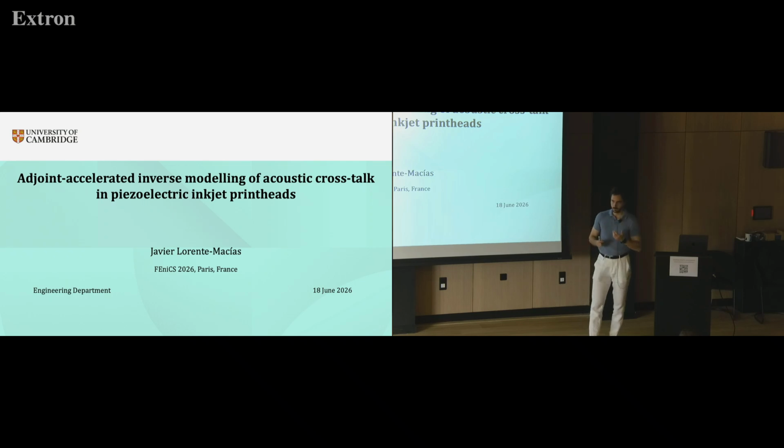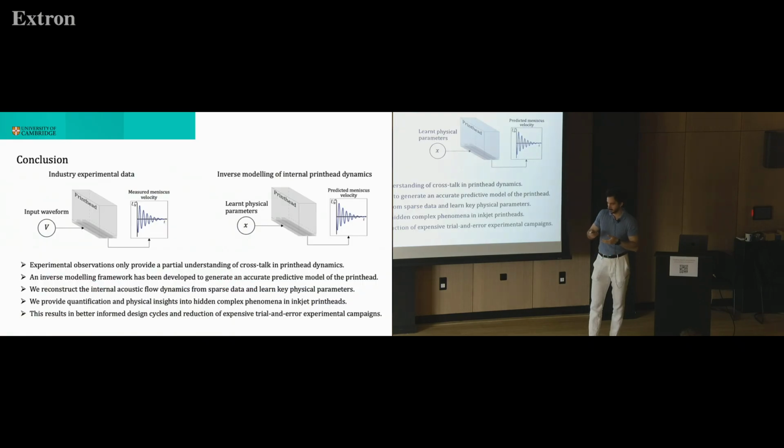But there are experimental data that show that once the droplet is ejected, there is a very thin, high surface filament that retracts back to the printhead very quickly. Or maybe it breaks up, or maybe you get satellites. There's a lot of data on ordinary inkjet printing of this type.